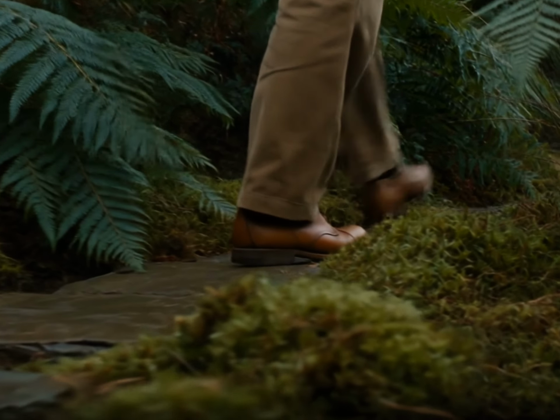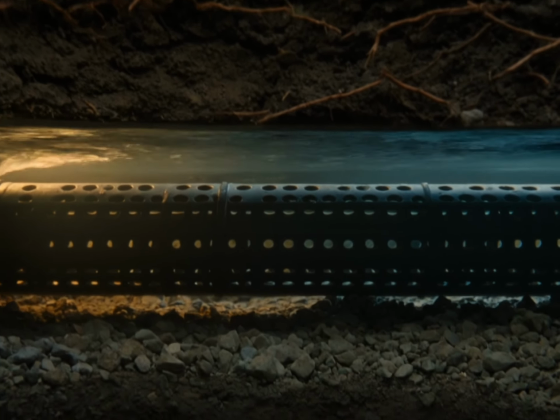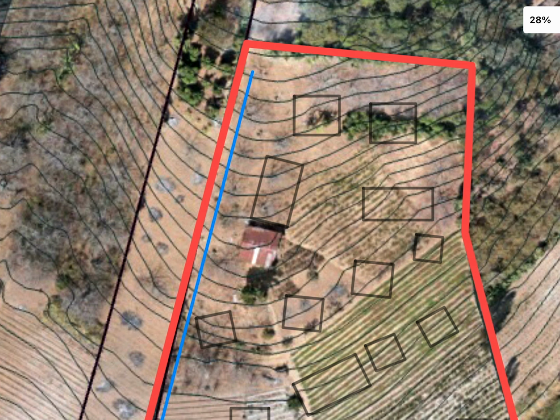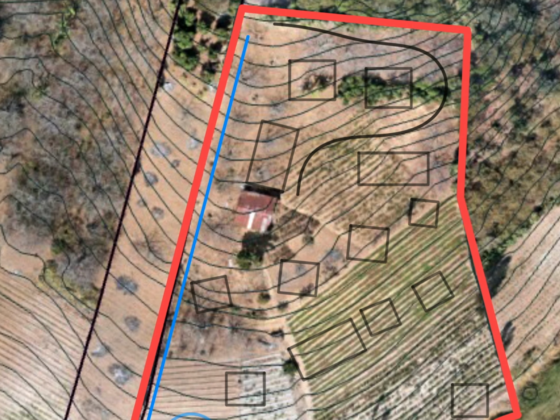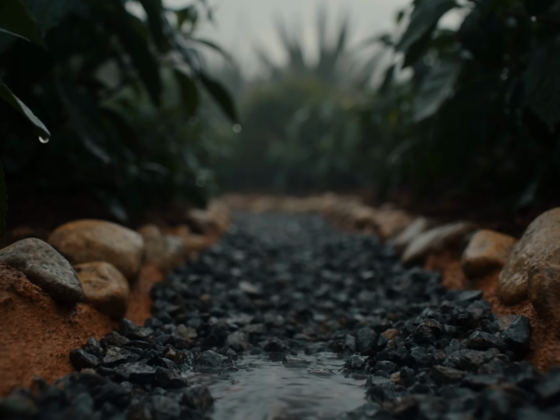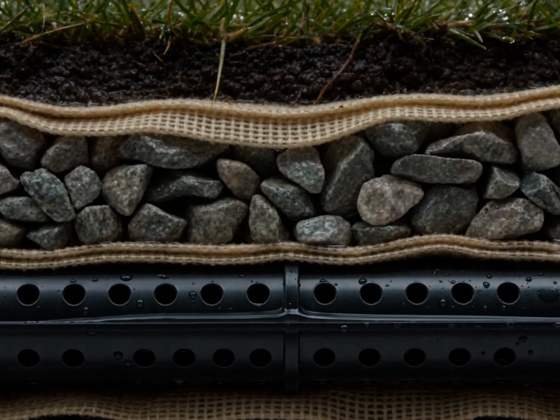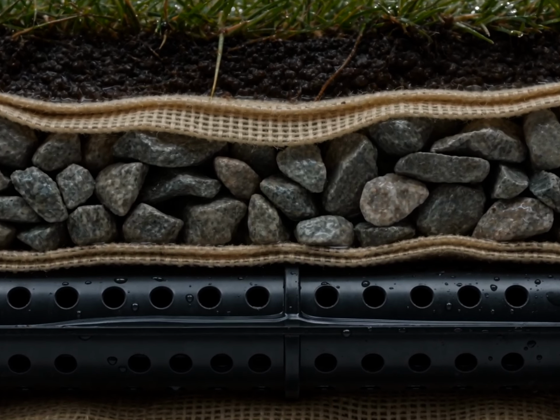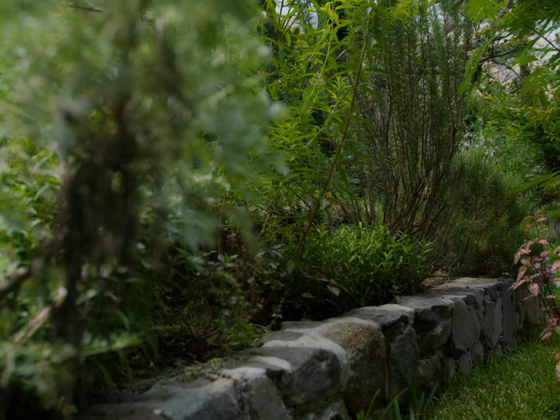Water and people both move on contour, so the drainage runs underneath the pathways before they switch back up the hill, and the most productive spaces sit right alongside where people are moving. Paths follow contour, winding across and switching back. Underneath the path, a French drain. Same line as access, drainage, and food forest edge.